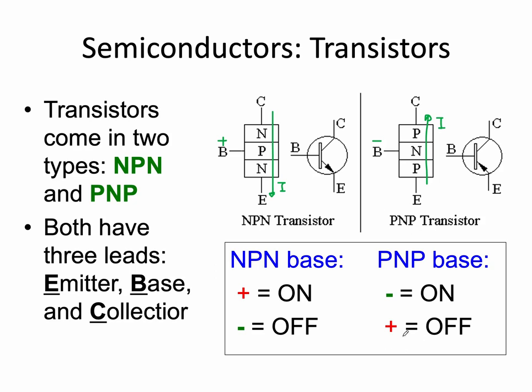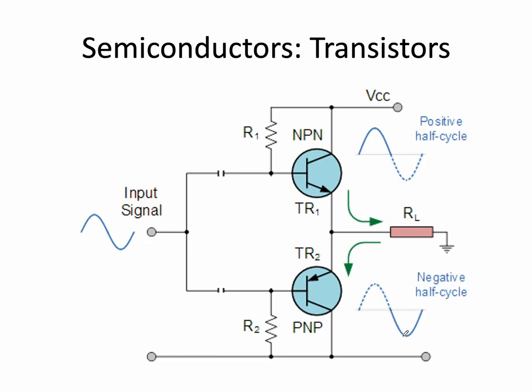And you can even turn them partially on and partially off, which is where you can actually make an audio amplifier. If you take an NPN transistor up here and a PNP transistor here and run one of these signals into it, when it goes positive up here, it'll turn on the NPN transistor. This is the base of it up here.